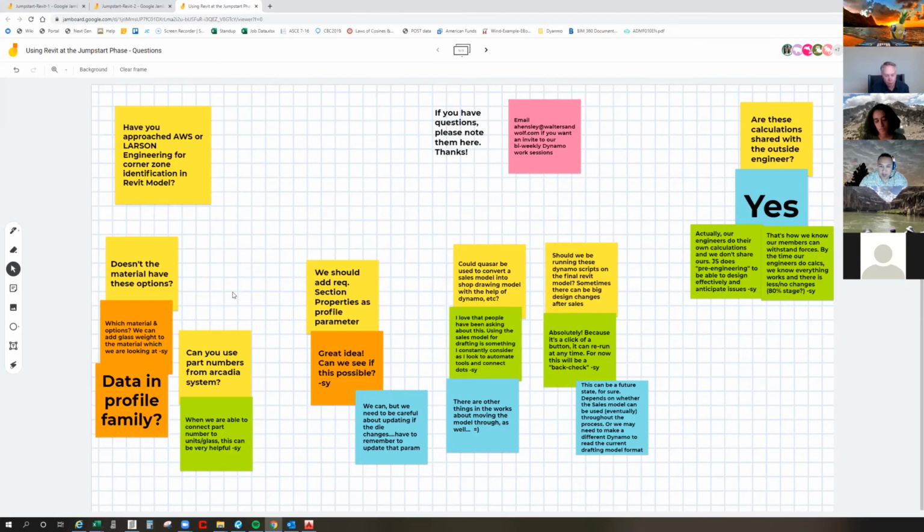I mean, we just take every corner zone, and I think the estimators even interpret that themselves, saying, okay, they go around the building. If they have 4 corners, they just estimate that each of those corners and the first 2 mullions, the first 2 bays at the corners, need steel reinforcing, and just estimate in that fashion. Yeah, those wind tunnel studies can be super different, expensive and precise, and completely different from the standard way to look at a building for corner zones.